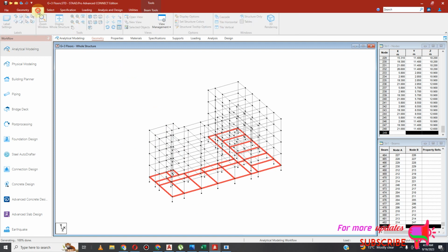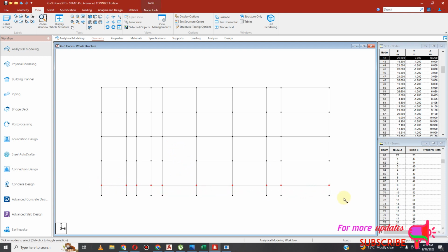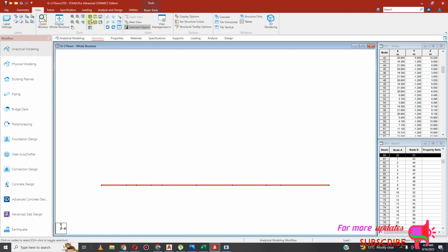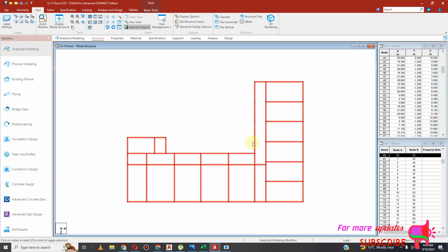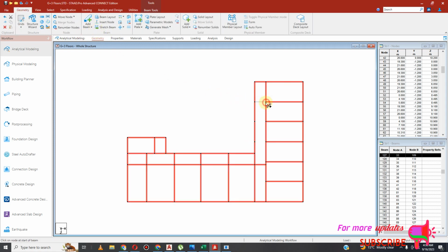So I can go to side view, then I'll select that floor and select beam cursor, and then I'll select this floor, then view, you select objects value, and then remember there's a beam here because this balcony needs a beam, so beam there, beam there, beam there.